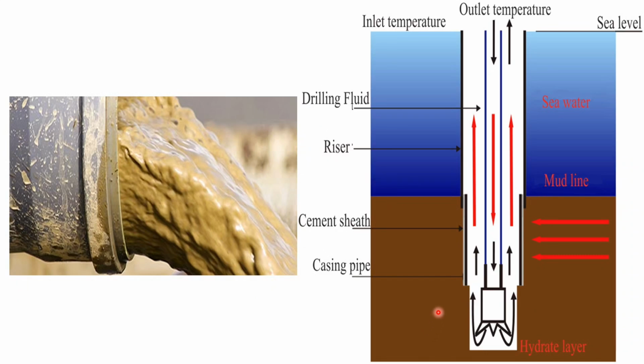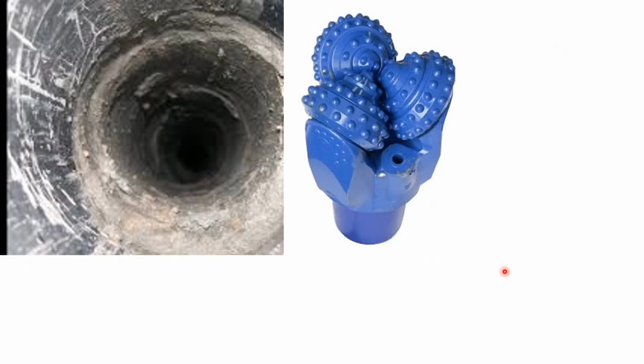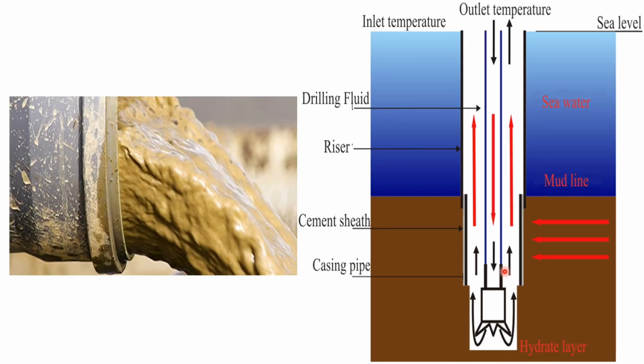Okay, and the temperature logs are also necessary to make corrections for the water viscosity and also the specific conductance. Water from different aquifers generally differs in temperature, so the source of water and the movement in the hole may be identified from the temperature logs. And then we'll go for the fluid movement. So the fluid movement is something like the direction and the velocity of the fluid moving within the borehole, and that can be measured by logging.